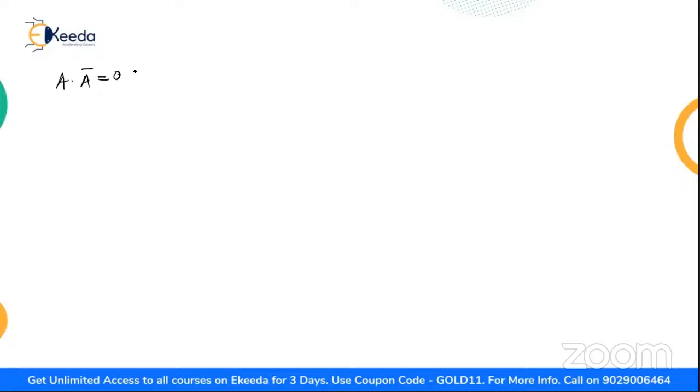So A dot A bar is what? 0. How can you see that? That is A in series with not A. Not A is equal to 0, meaning open. So this is A in series with not A.